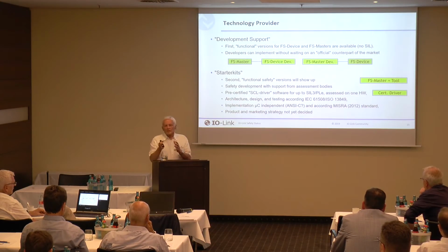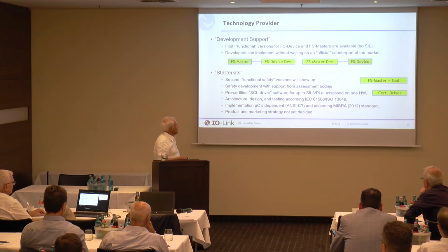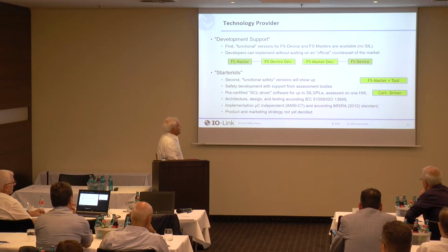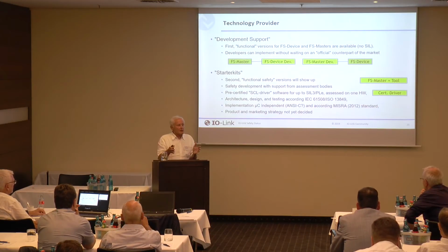So architecture, design and testing. Architecture for CL3, for example, it's a must that you have redundant microcontrollers. How you design it, it's up to you, but there has to be some redundancy. Then, of course, these drivers have to run in different microcontrollers.